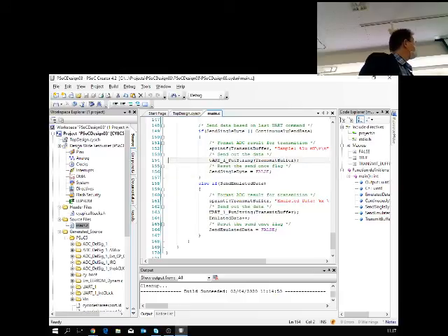And then basically, what does it do? It just makes the string using sprintf to the transmit buffer, sample %lu, so it's long unsigned, I think, in millivolts, and this is carriage return line feed. Yeah, and then the value, and sends it to the transmit buffer.